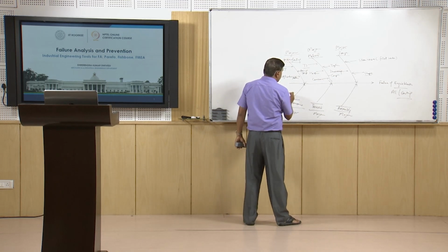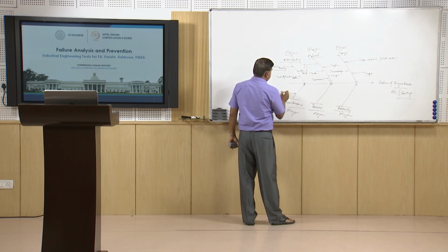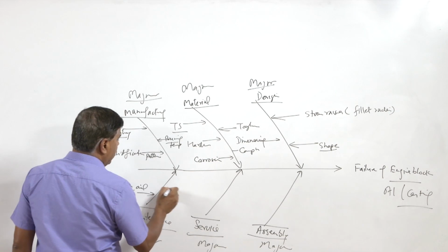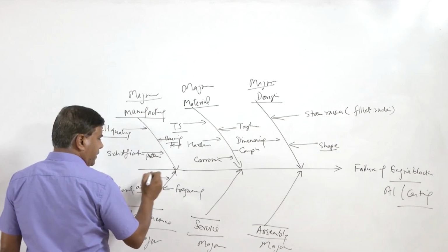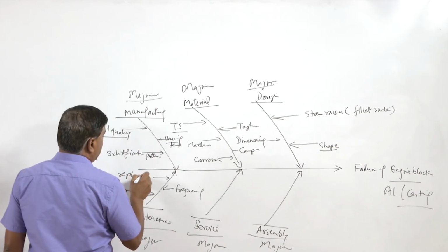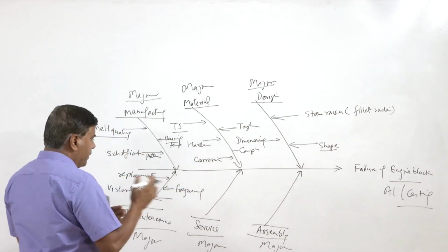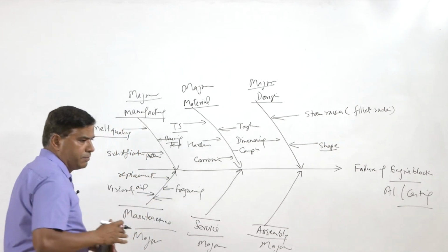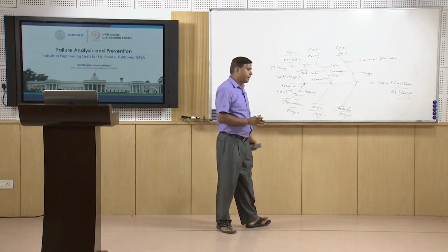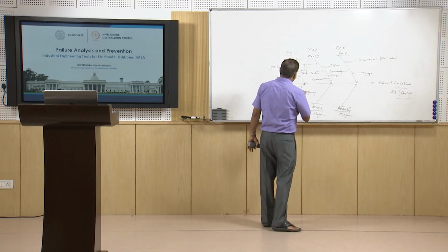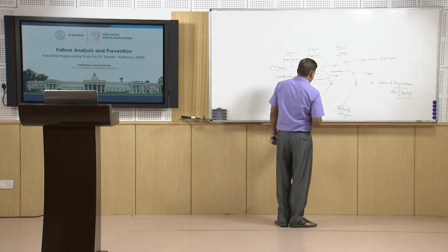Similarly, in case of the maintenance, we need to mention the kind of viscosity of the oil to be used, the lubricating oil, the frequency of the oil to be used, and the replacement and repair of the things which need to be done after a particular period of time. Like in case of the automobiles, it is like 2000 kilometers or 5000 kilometers. Similarly, oil is to be replaced after a particular 1000 kilometers of the distance. So, all those things need to be specified so that the engine can keep on working properly.